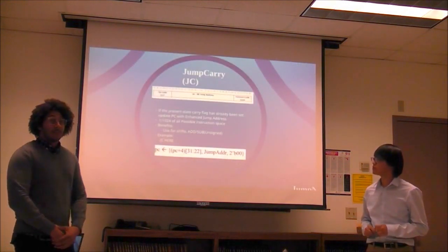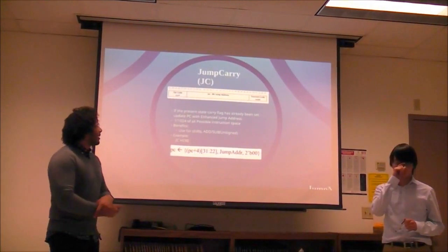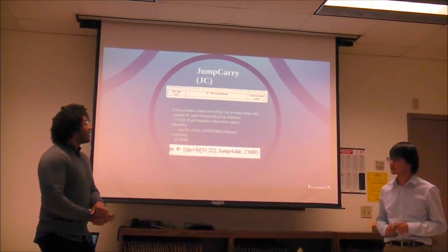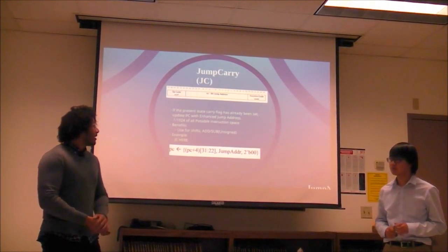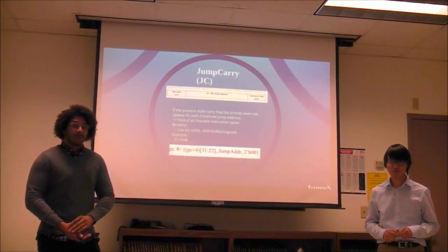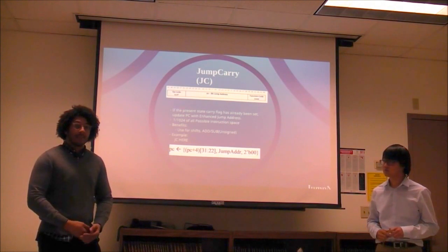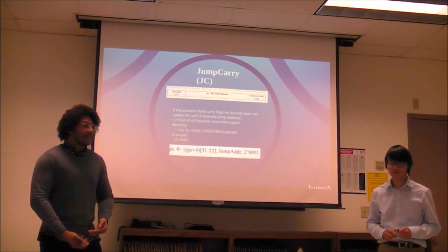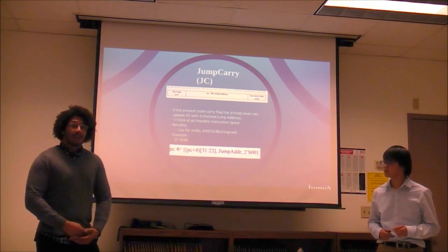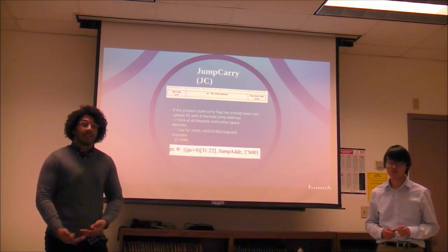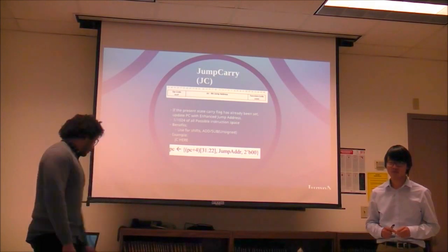So we did a jump if carry. This is the format. We are using the jump address, which is the middle 20 bits, and our function code is 00. This allows us to jump to 1/8 of our instruction memory space. This is beneficial because now we can jump further than our previous branches, and it allows you to jump based on whether there's a carry from one of the shifts or from an unsigned arithmetic.